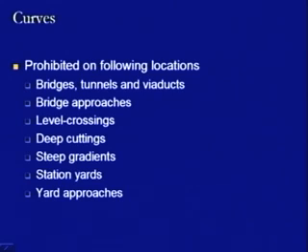In the case of deep cuttings also, a curve should not be provided, because it increases the length, and when the length increases, the cost of cutting is much more than the cost of embankment. It has its economic or cost consideration.